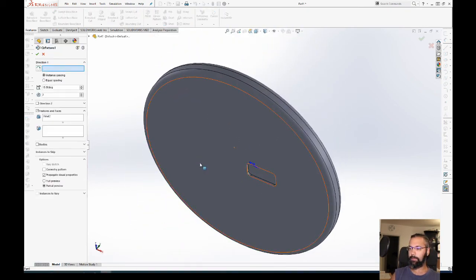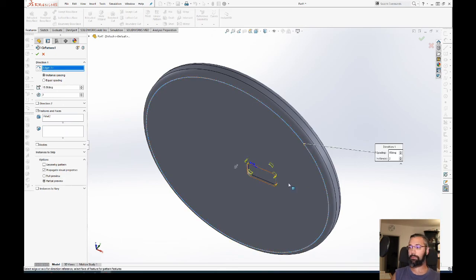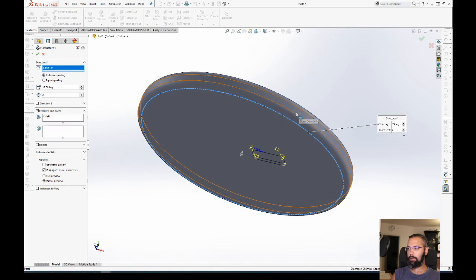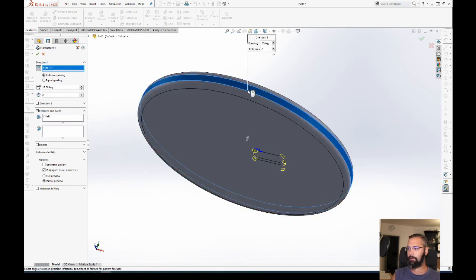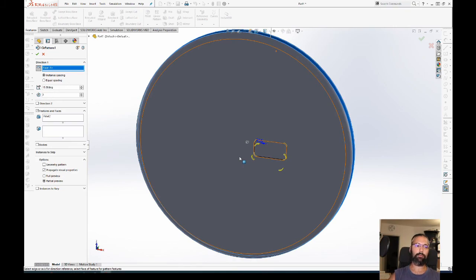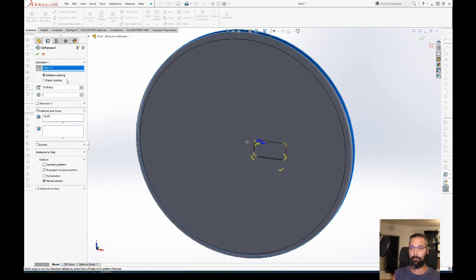Now, a circular pattern, instead of me drawing 3 times the same thing, it does it around a circle or along a circle. So you can pick this. You just need to pick an edge. You can also pick this face, I believe, and it will do the same. Yeah, you can also pick a point, but I would rather do it with an edge. The edge will be carried over to whatever we do later.